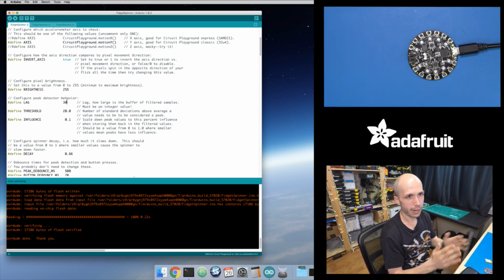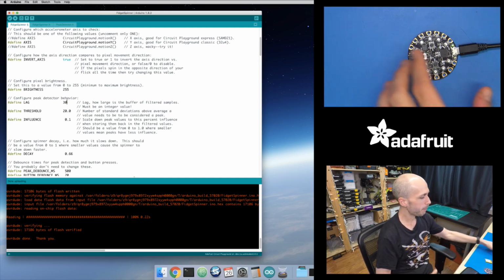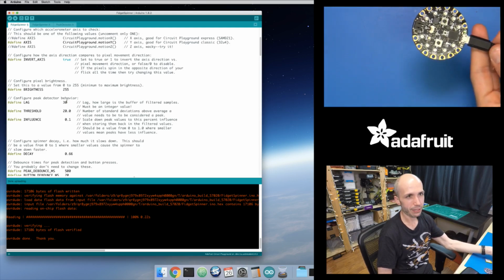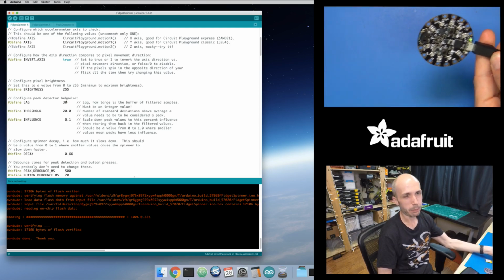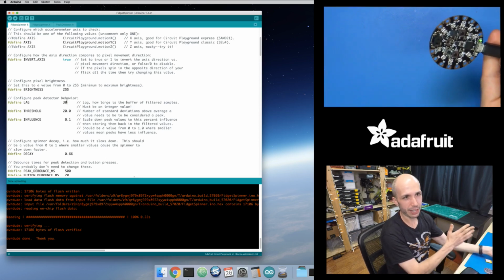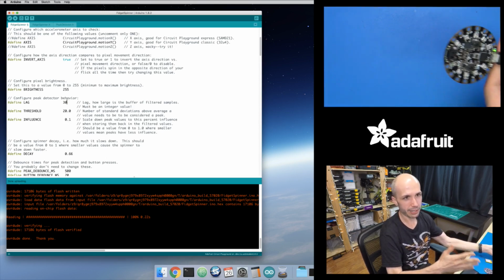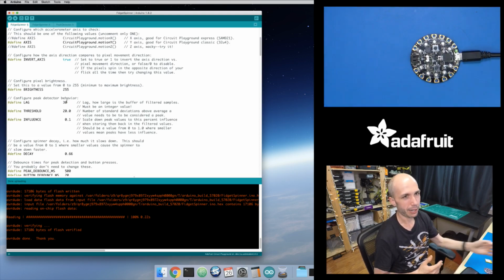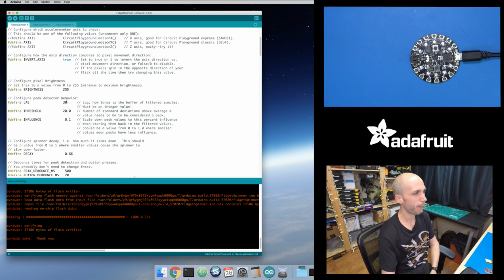The larger this value, the more samples you're going to average together, so it slows down the behavior in some ways. If this is attached to a car or a motorcycle, something that's vibrating and shaking a lot, maybe I want to increase the size of that window because I'm naturally going to have a lot more noise that I want to filter out. So I want to increase the length of that window so that I get more values to average out. Whereas if it's just static and sitting on a desk like this, maybe it's not seeing as much force, and a smaller window might be okay.